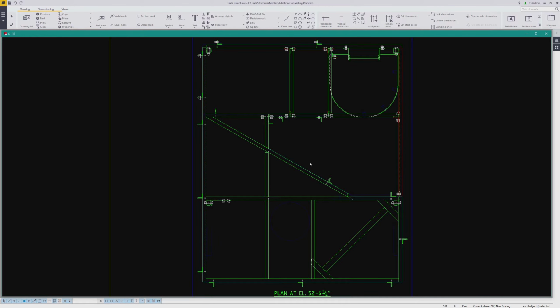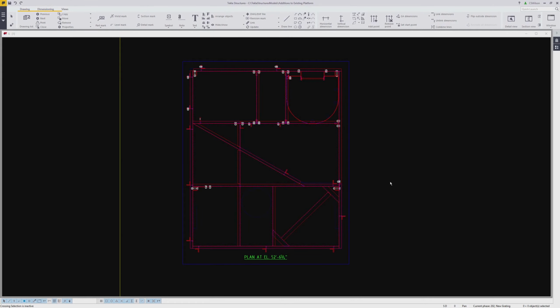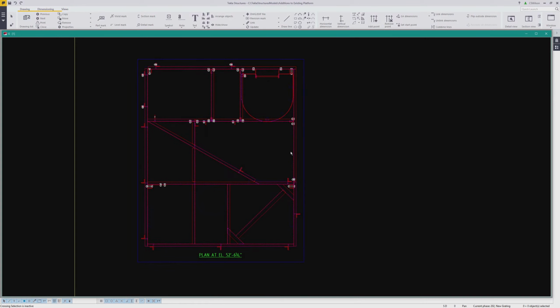And that should just about do it for that. I'll briefly show the steps I use to create object level filters just to illustrate how that works. This is version 2016, but I still use the old method for creating object level settings since I really haven't had time to play with the new method. And for the purposes of this demonstration, I've changed the color of all the objects to make it easier to see what's going on. We'll start by double-clicking on the view to open up its properties.